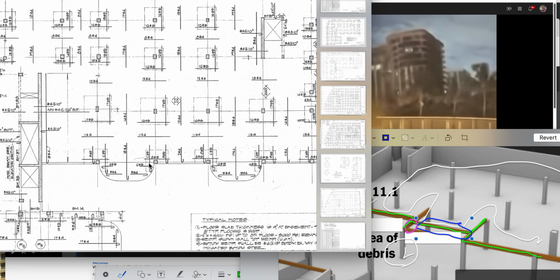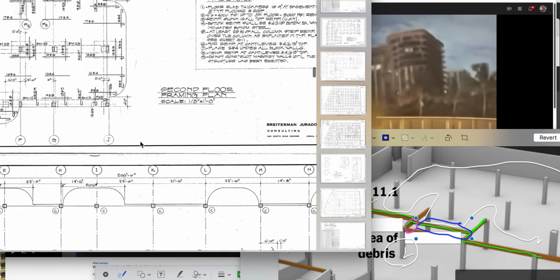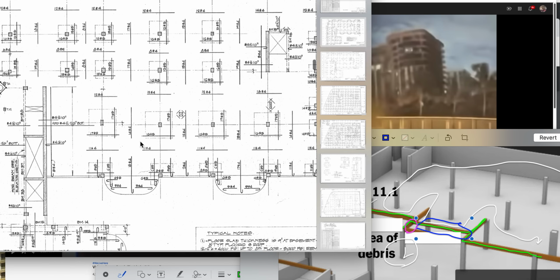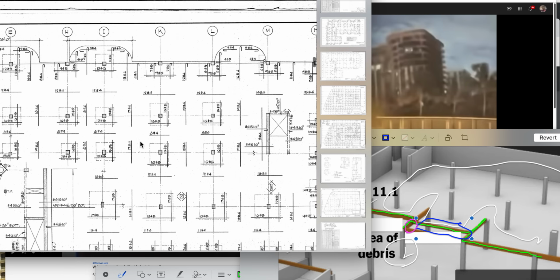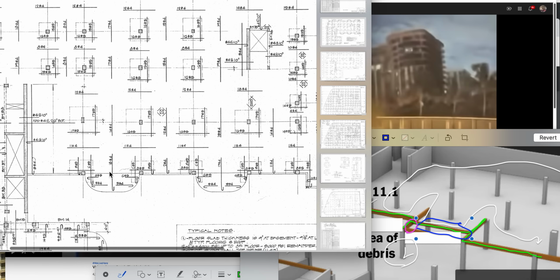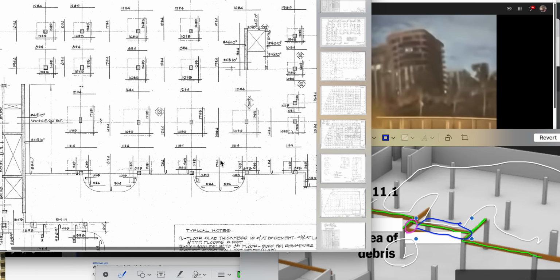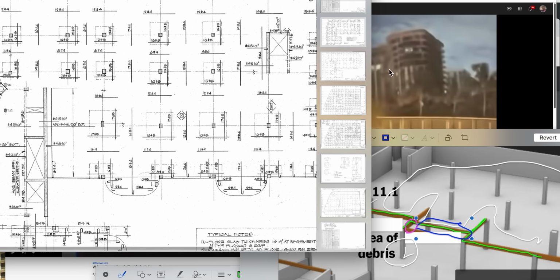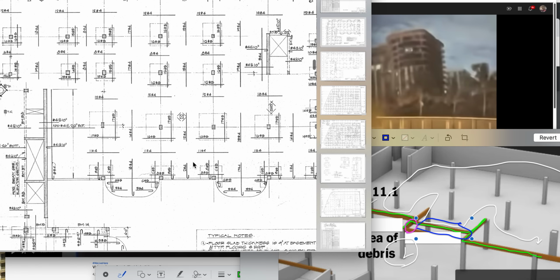There's a wall, the party wall between K and L. Not a party wall, a partition wall for the bedrooms, and that's probably a decorative way so you can butt it up against something. It's still transfer. It's still a nice indicator of what's going on in these floors at this point, of what's falling more so than not. There's an internal failure on the back side of it. G is pulling down. It broke away from G at that point, I believe.